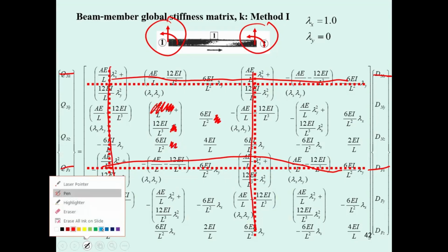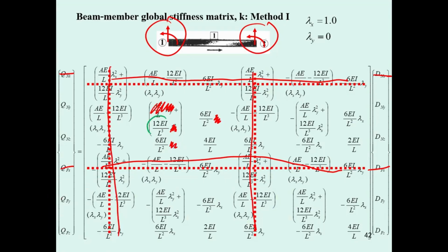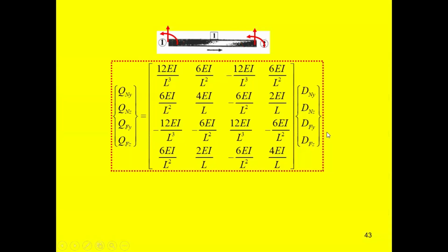So the important coefficients for the beam are going to be 1, 2, and 3. And then you also have this one, really easy. This one is 4. Only 4 coefficients are important. Let's simplify this to this matrix. Now, this is going to be the small k matrix. You are going to derive it by yourself.